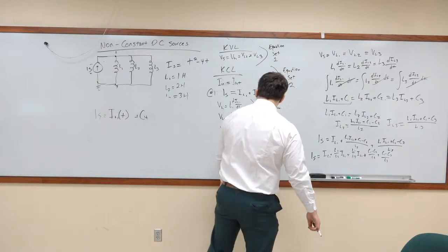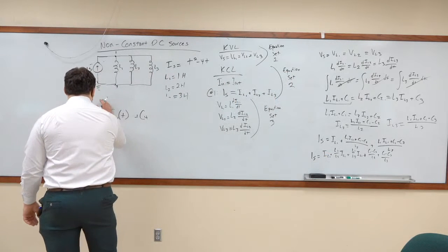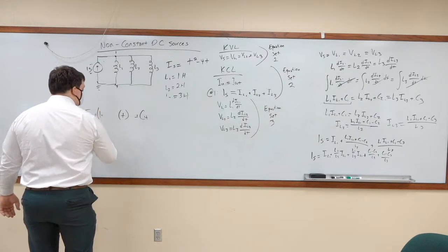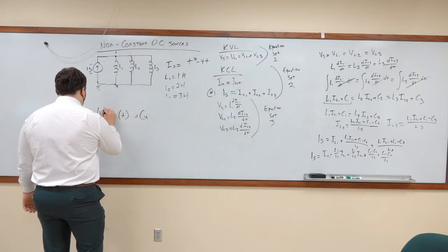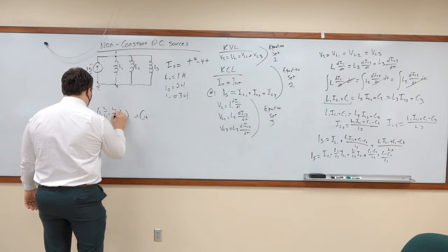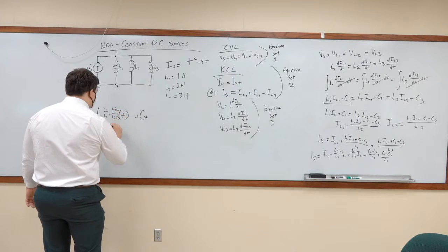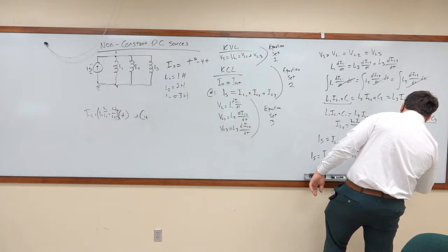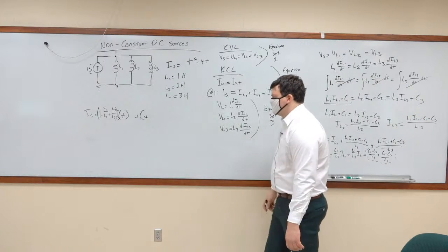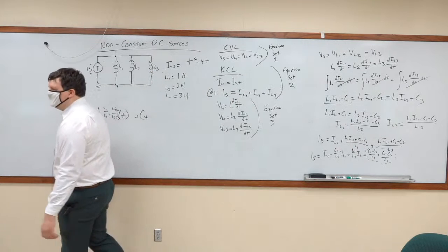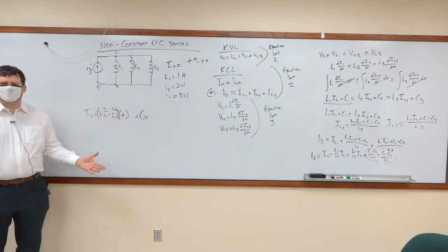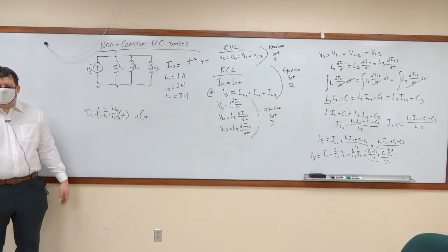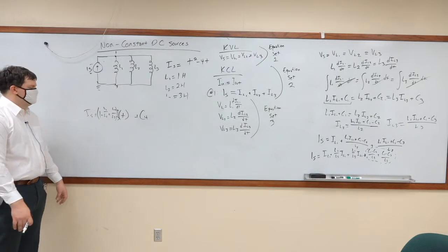Okay, and then this IL1 also happens to be, I guess I should write out the full equation. IS is equal to 1 plus L1 over L2 plus L1 over L3 times IS. And then we add C4, where C4 is just an amalgamation of all of our constants, okay? Trying to solve this without using equivalent inductance, which is what I did for the last problem with the equivalent capacitance. I don't know, there's no one right way to solve a problem. I just happen to be doing it the hard way.